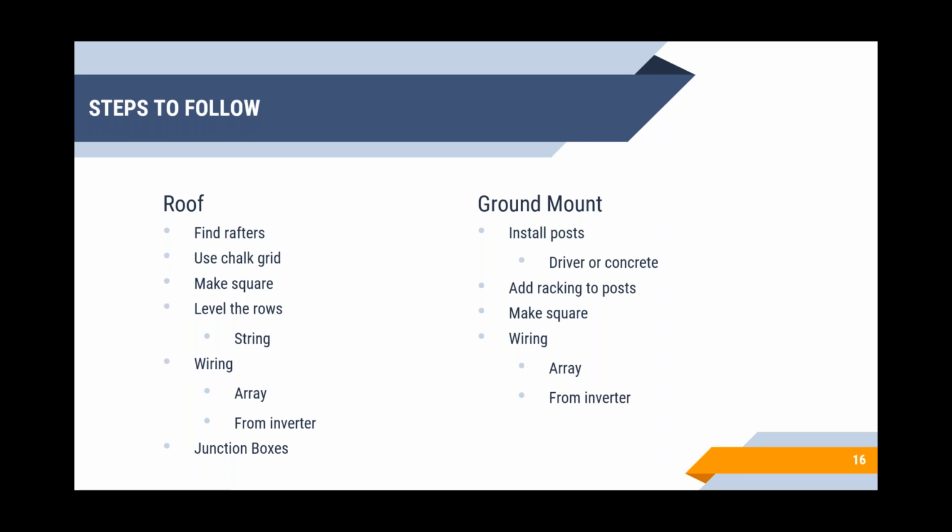One thing that we learned that's most important out of both ground mounts and roof mounts: make it square. Everything has to be square because every step you take has to be perfectly square, because the last point of the install is laying down modules. Your modules are square, so if your racking isn't square, you'll run off your racking or it won't have the best looking craftsmanship. So make sure that you have all of your feet and racking square and take your time with that.